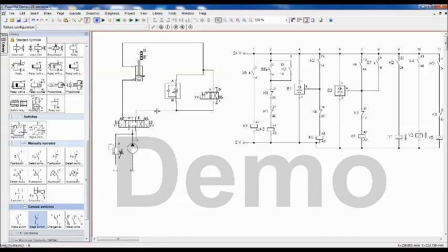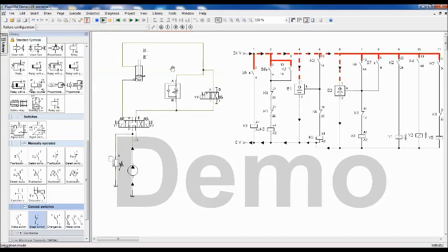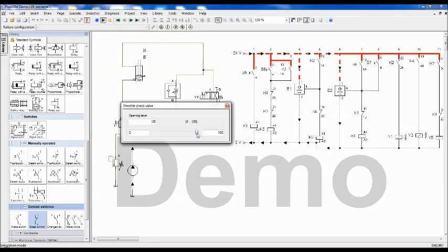So what I'll do is we'll have a simulation, but in this software there is some problem. That means if cylinder velocity is very high, there is no detection of B1 and B2. Sensor detection is not there. So that is why you don't find the speed change. So I will reduce the speed to very low.